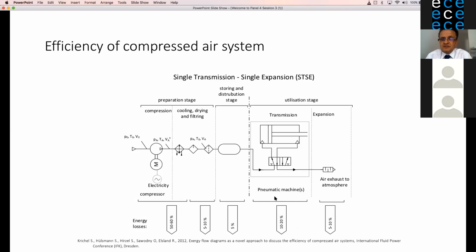Just observing the pneumatic cylinder, I mean its dynamics, we found that it is possible to put in a small amount of back pressure to slightly change the characteristics without perturbing the normal work of this cylinder.